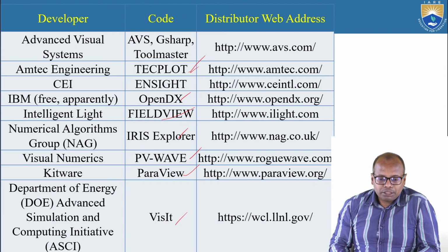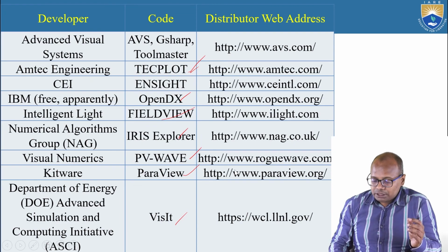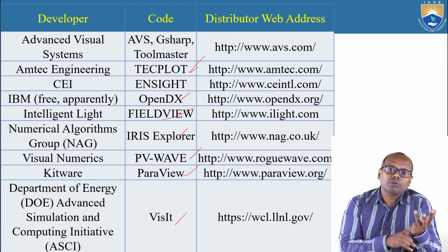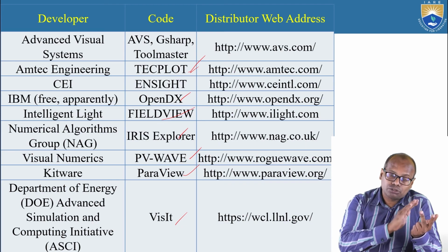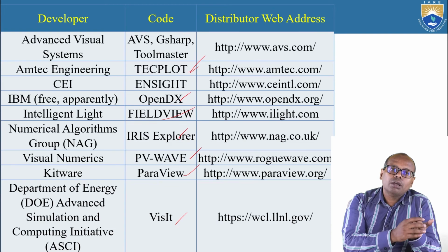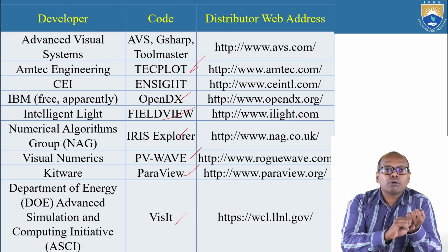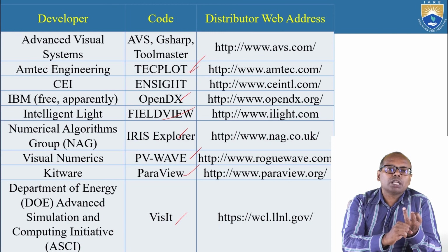So this is about the process. What we have discussed till now, we'll just have a recap. First we have to identify the problem. Once we have identified the problem, we have to identify the easiest way to solve it, what the domain should look like, what the boundary conditions and input conditions are, what the appropriate meshing technique is, and what turbulence model I should use.